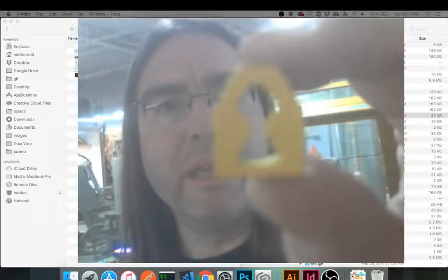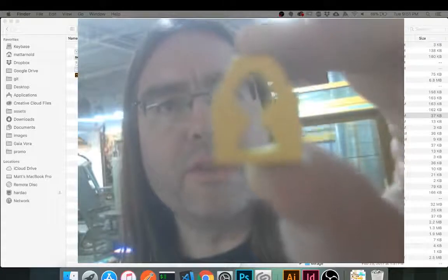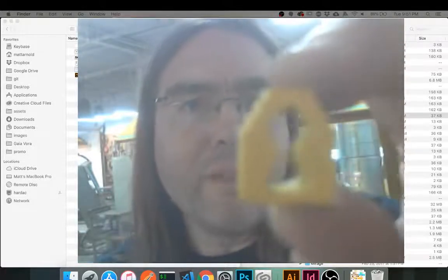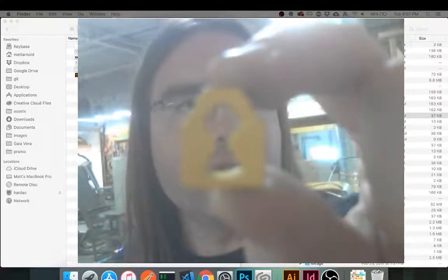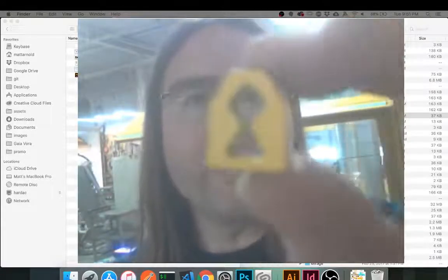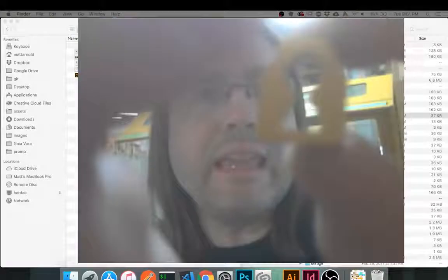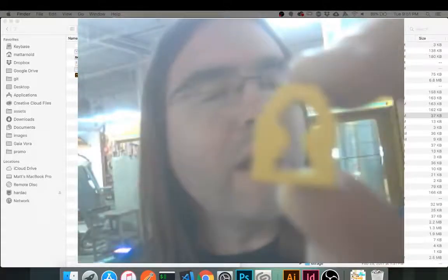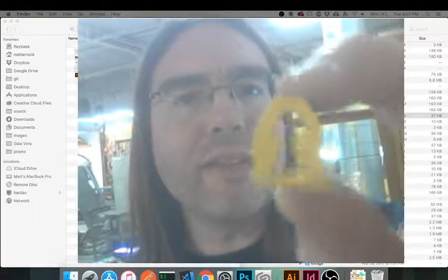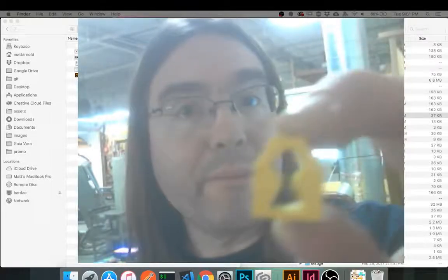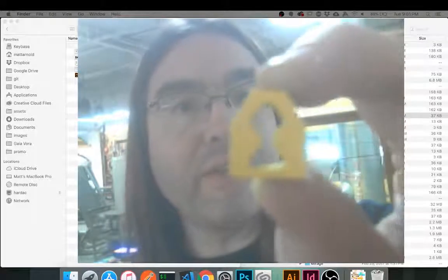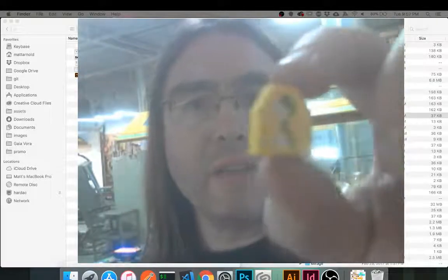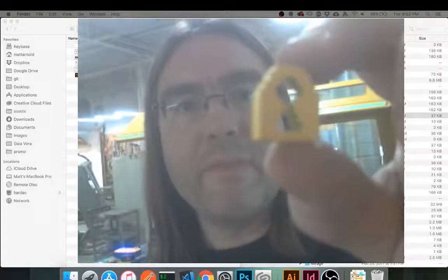Because if you have a mill, then the mill bit, that basically is a drill bit, it drills down into there, and it's round. Drill bits are cylindrical. They're round. And because they're cylindrical, it would actually leave a rounded interior corner there, as it would have milled this out. And it didn't, because it used a laser beam, which was incredibly thin, so thin that you can actually create a sharp corner.